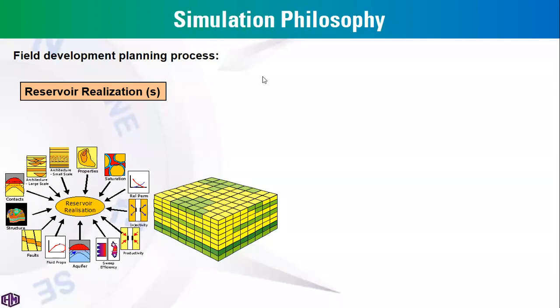This is simply the philosophy of simulation. We have several reservoir realizations in terms of all subsurface data, like the reservoir description, fluid and rock properties, the saturation functions, relative permeability data, aquifer data, and reservoir structure, subsurface horizons, and the fluid contacts, and so on, and the facies distribution.